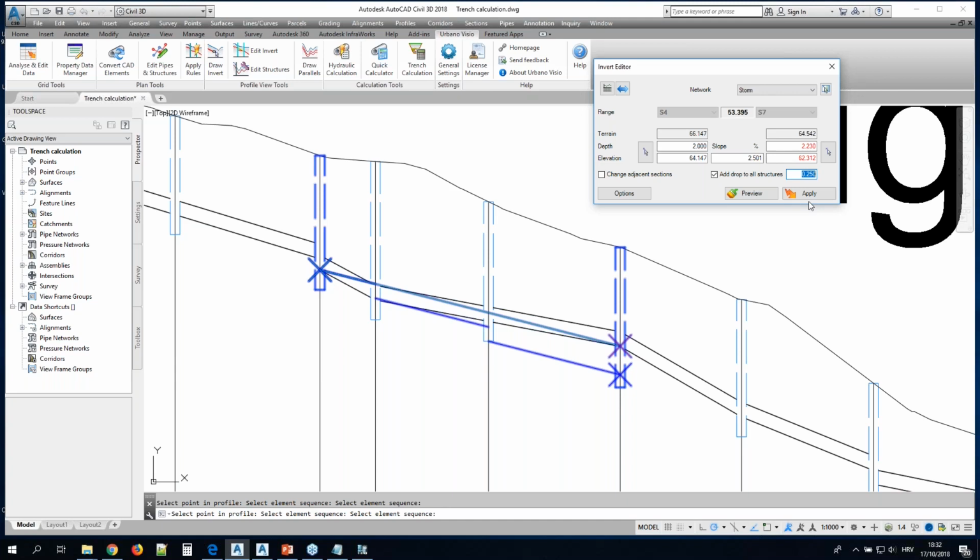In this case, as I said, this is a metric profile. So in this case, it says 0.25 meters. And of course, I can change it. So if I say 0.5, you will see the big change. And the program basically tells me, okay, this is your slope if you don't add the drops, and this will be your slope if you do add the drops.